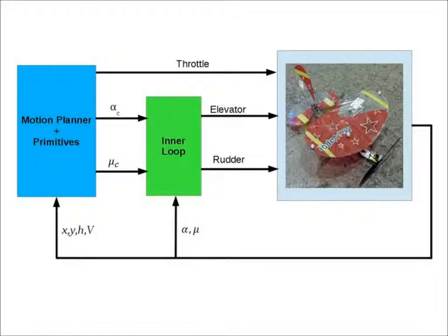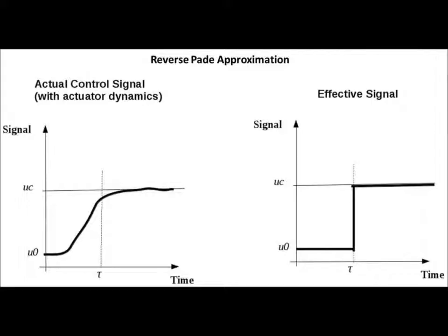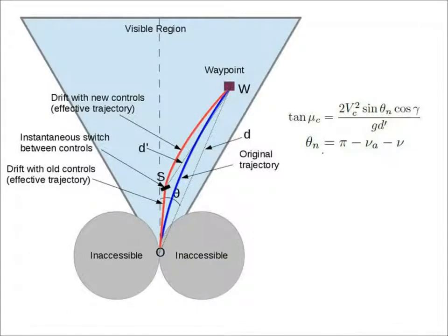the prescribed values. In order to accommodate the actuator dynamics as the aircraft transits between two successive primitives, we use a novel time delay-based formulation which allows us to derive algebraic formulae for the control inputs required to fly between a given pair of waypoints. The computation of the control inputs is simple, fast, and easy, and duly accommodates the dynamics of the vehicle.